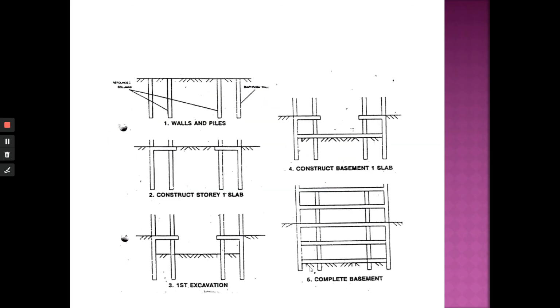Let's go to the illustration. So this is the illustration. The same thing. You will have the retaining wall. Here it says diaphragm. Okay, and then you will have pre-founded column. The same step. The second step, you will build the floor slab. Remember, at the top down, you cast a complete set of the slab. But this one, they leave a space.